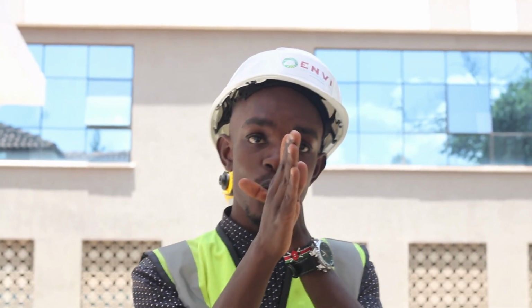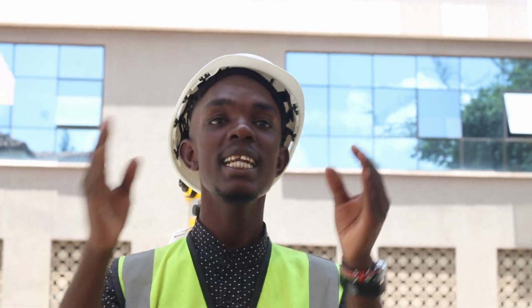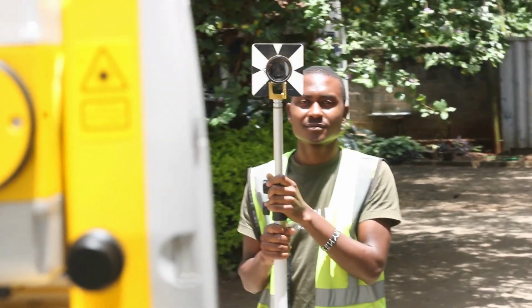Once it reads 0, I'll take the prism and ensure that I can see the chainman in line with the 0 degrees. It doesn't matter whether he is where K1 is. We just need to focus him to be in the line that the total station is. Do not move the total station provided the change in horizontal angle reads 0. At the moment, it reads 0. Now I'll have to move the chainman until I can see him. Once I see him, I'll measure the prism and know the distance that I'm supposed to move.